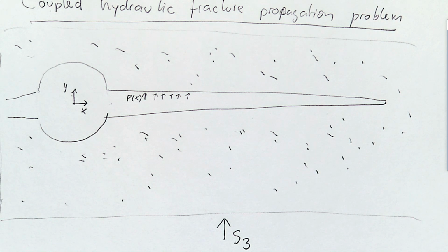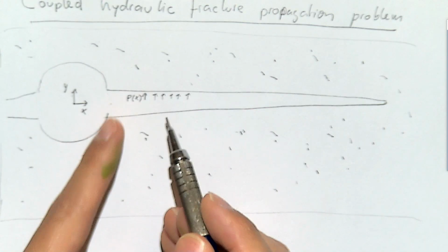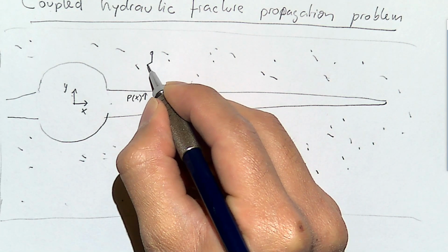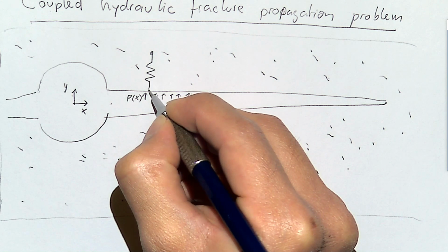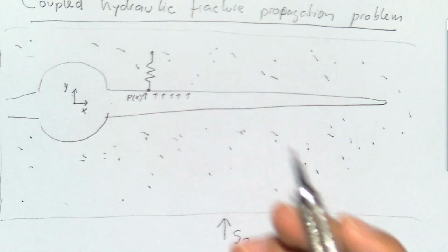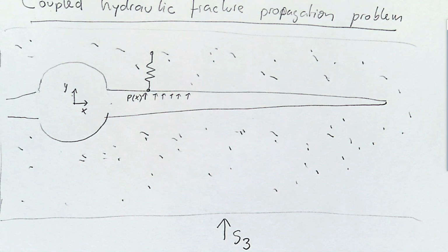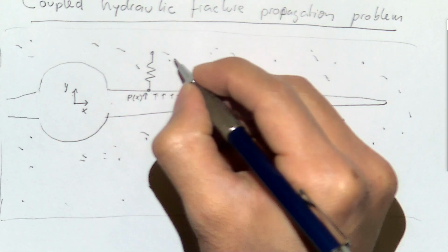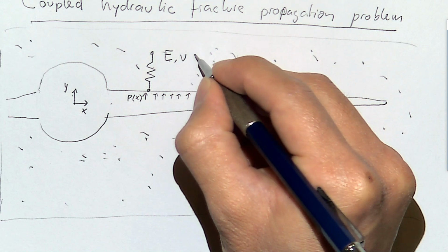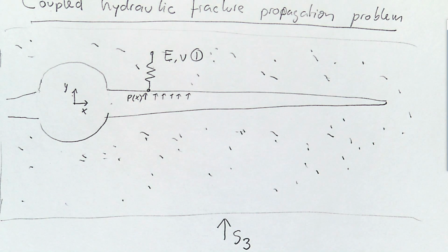And in order to open a fracture, you need to apply a pressure on it. And the rock, since it is elastic, is going to act as an elastic medium. Imagine that this rock is several springs: the more you press against them, the higher the stress they oppose to that fracture. So every time you open them a little bit more, it's going to be more difficult, or you're going to need more pressure in order to open up more.